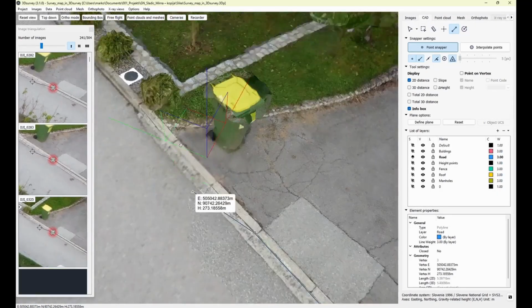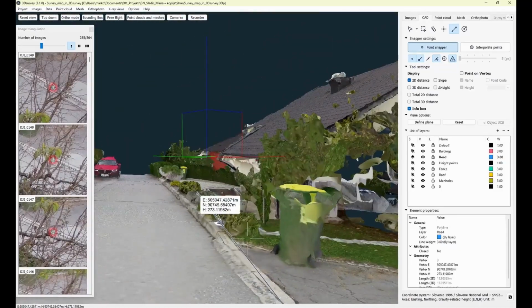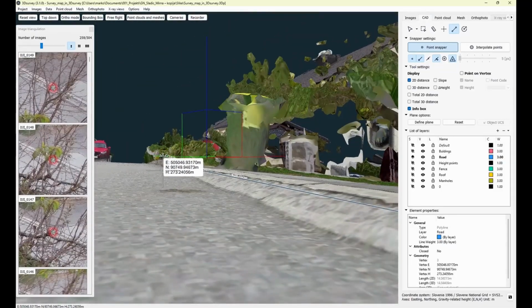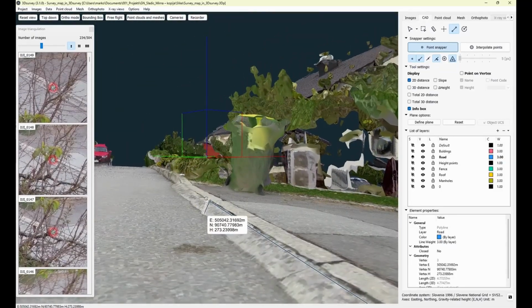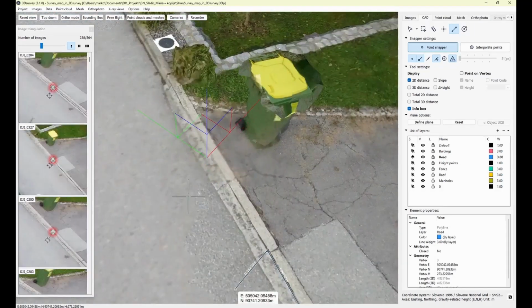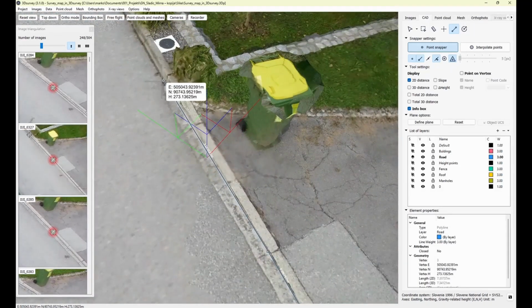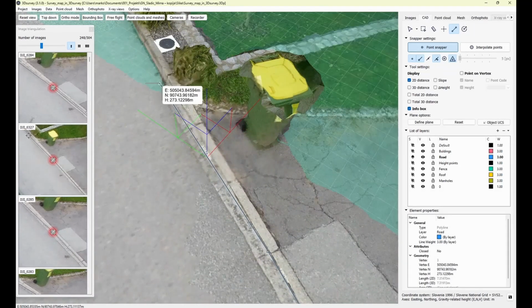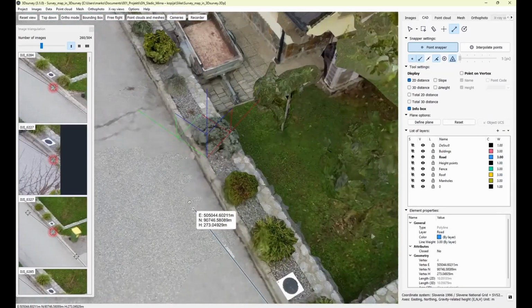Here again, it's a lower curve. Because of the water flooding, they actually added some material here. So I will step here, and again I will use my Q button to freeze the height 20 centimeters away from the curve, and then transform this height to the exact position.